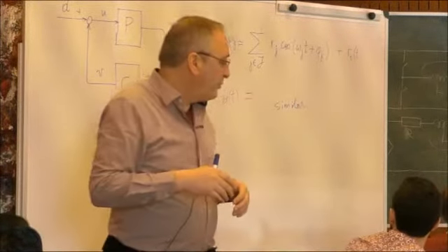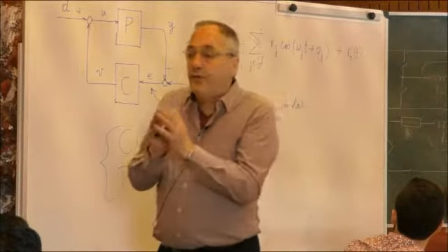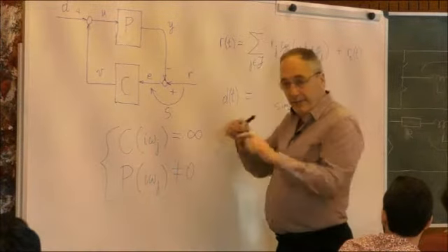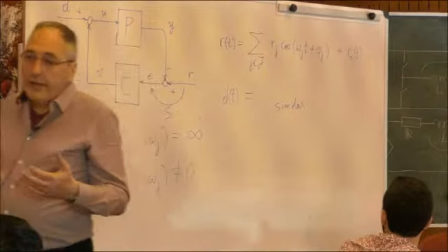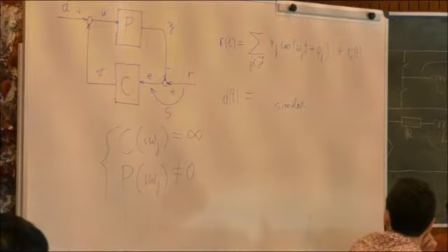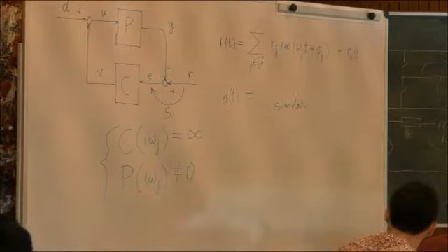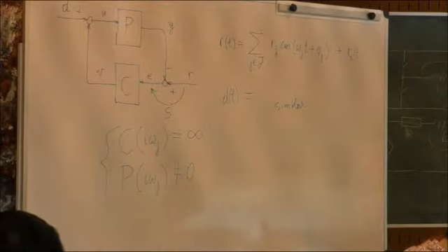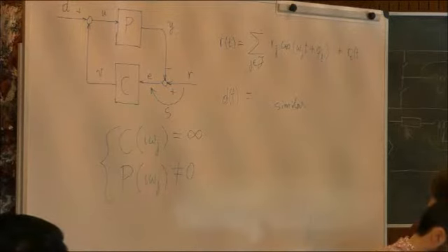So our criterion is not only to have poles at the frequencies that we care about, but in general to have the gain as large as possible, at least in the frequency range that is of interest to us. Not every frequency is of interest, but there is usually an interval of frequencies which is, and in that range we want the controller gain to be large, like always in control theory.